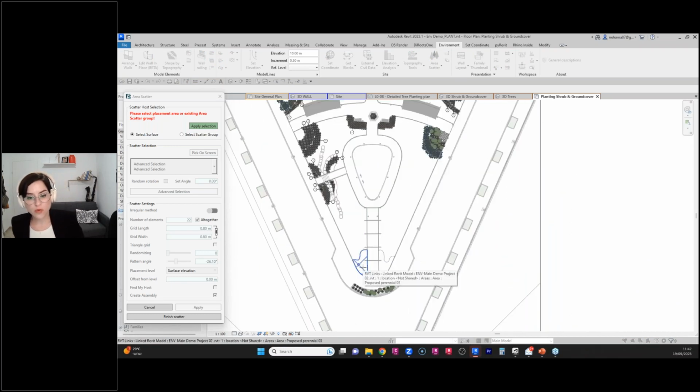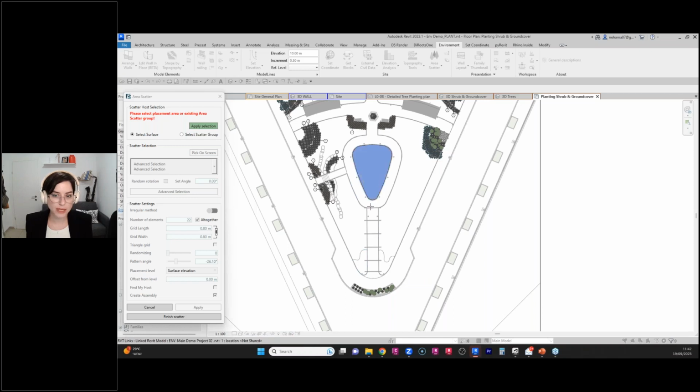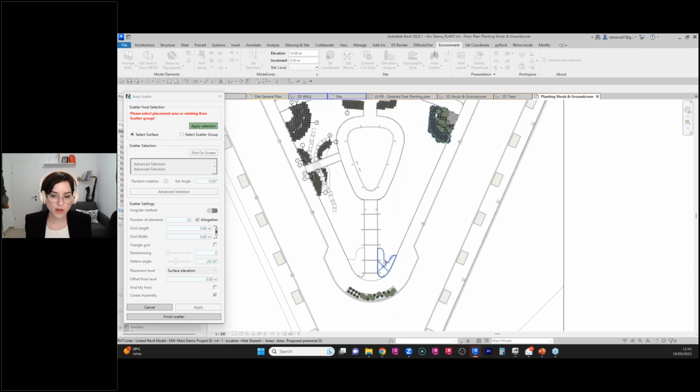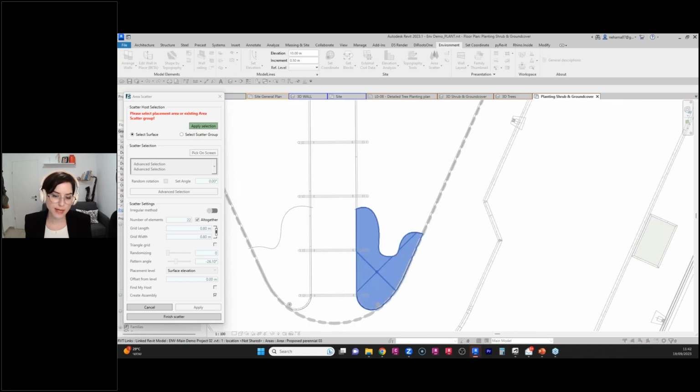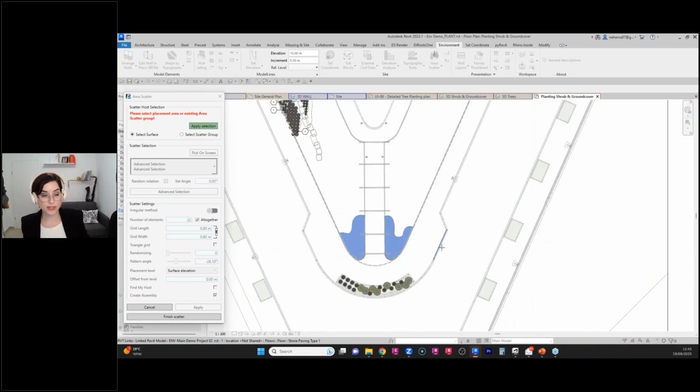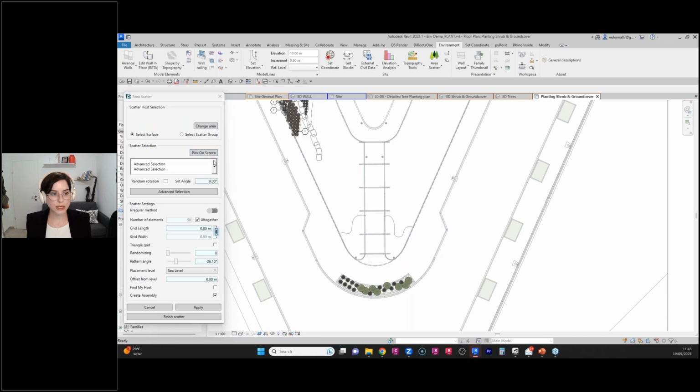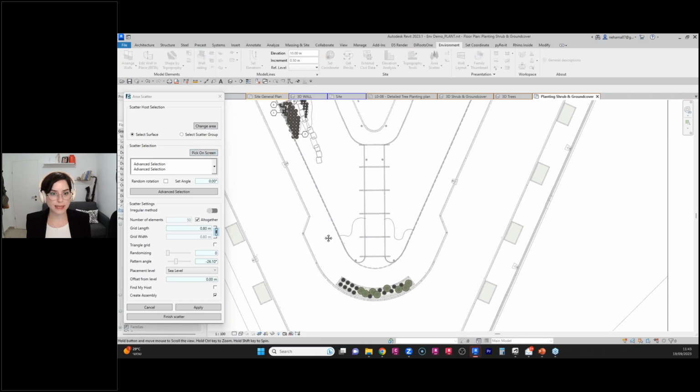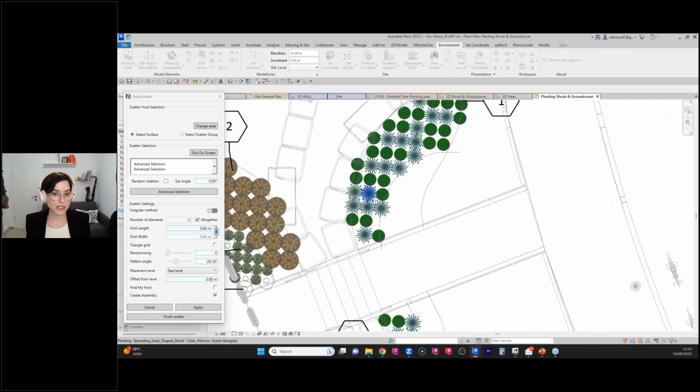If you're already using Revit, you don't have to have areas per se to place the families. You can place them on floors, on topographies, or just on areas. That's my favorite method, because it allows me a lot of flexibility in my design.